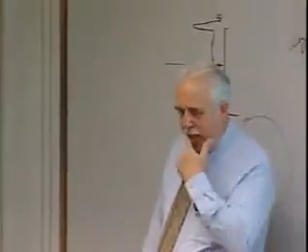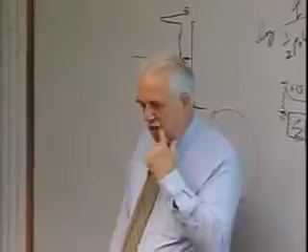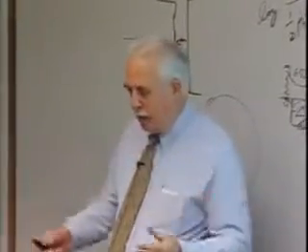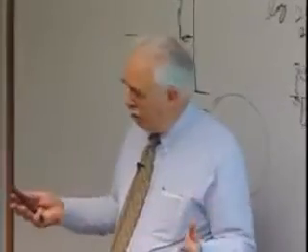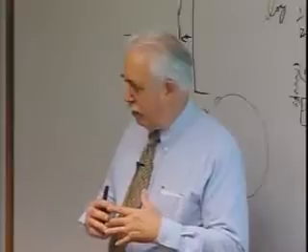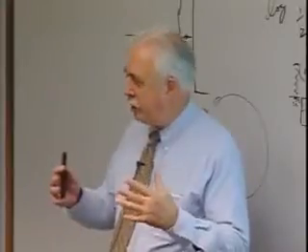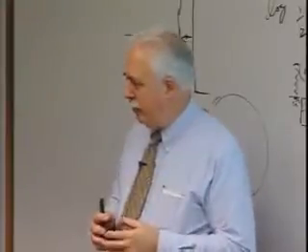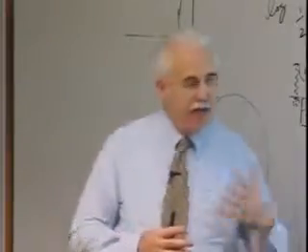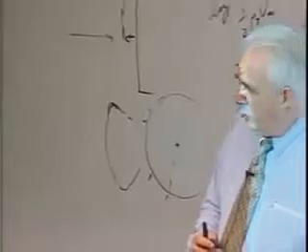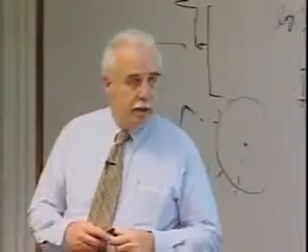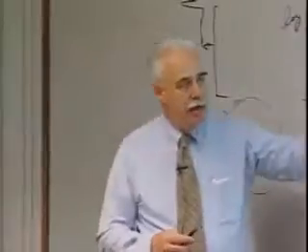Some of the people at Ames did correlations with velocity and with temperature, and there were numbers like temperature to the 8th power, temperature to the 12th power, because it's not limited by black body over a lot of the spectrum. And as the temperature goes up, there are more and more radiating degrees of freedom. It gets much closer to a black body. The radiation becomes dominant on Mars return, the radiative heat.